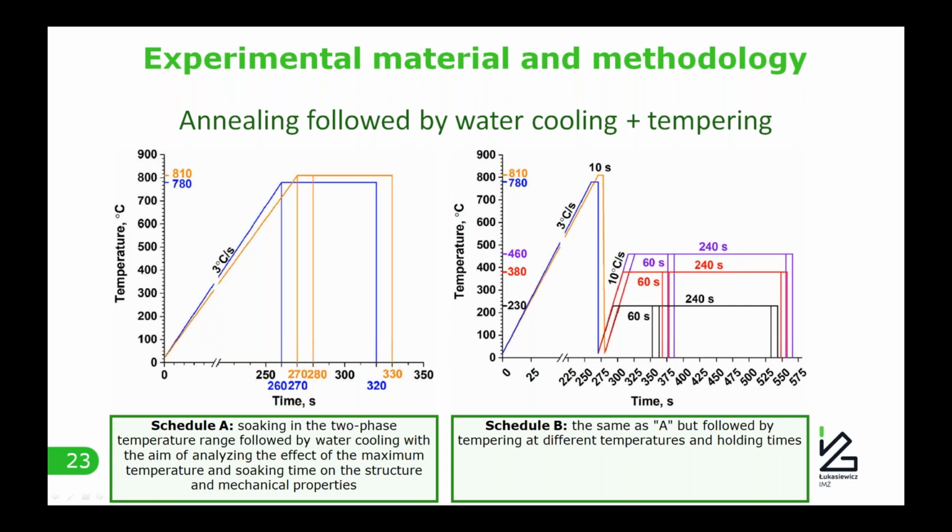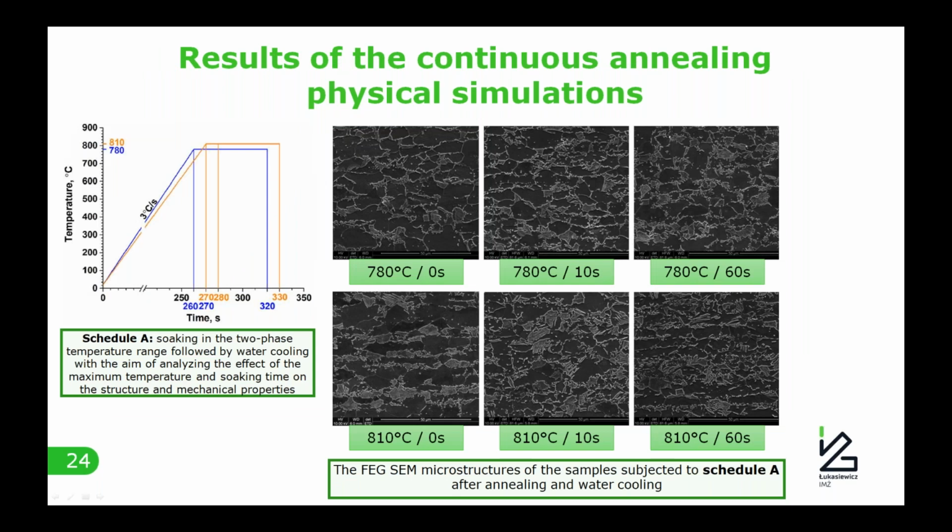Okay, and that goes into the next question: what is the maximum cooling rate possible in a continuous annealing line? And did you use that same cooling rate following the Gleeble simulation? Yes, in the Gleeble, in the standard unit, there is a problem to control the water quenching. So we obtained about 110 centigrade per second cooling rate.